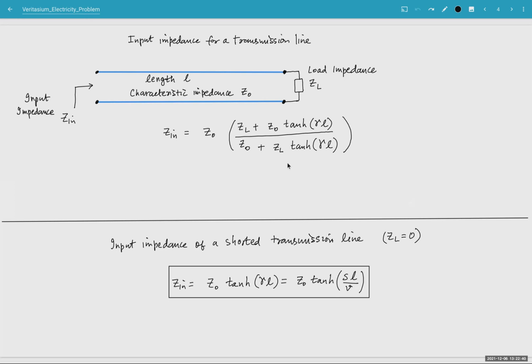In general, if it was an AC frequency, a harmonic power supply driving the circuit, and you were looking at steady state, this transmission line could appear as inductive or capacitive, depending on what phase you see for this impedance. But we are not talking about steady state response here, so frequency does not make sense when we are discussing this circuit. We're looking at the transient response for a step function input. So let's do that here.